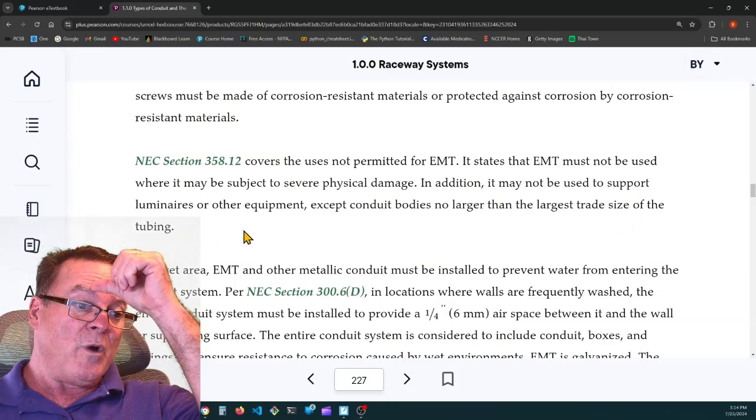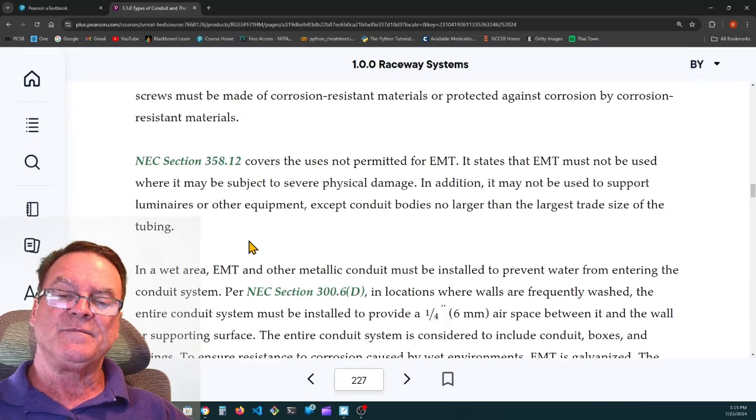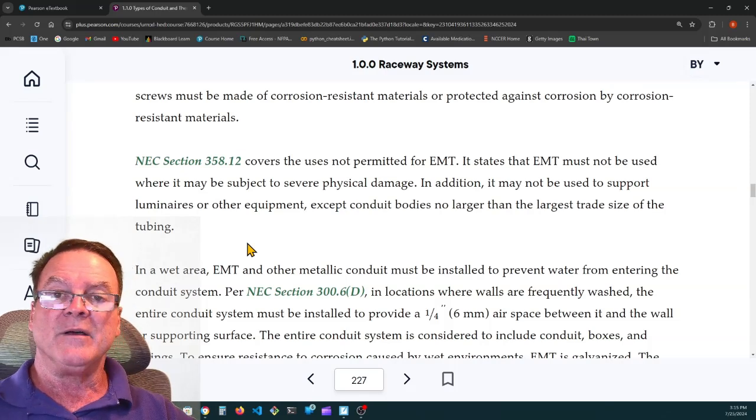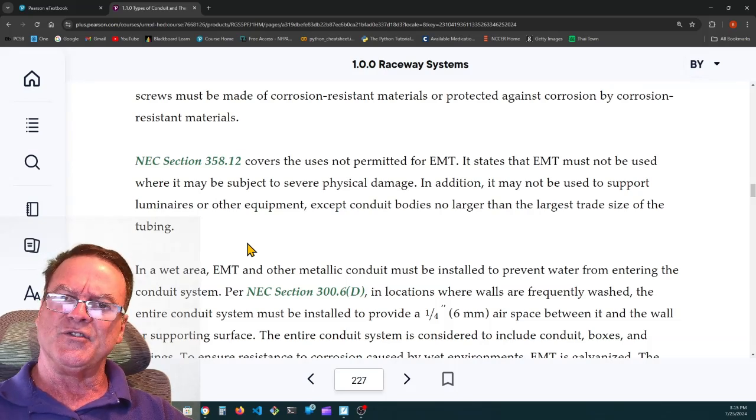So we use down rods to support ceiling fans, and they're 3/4 inch rigid. You can buy them in any length. Oh, they have certain lengths you can get. I think they're even inches, 2, 4, 6, 8, up to a foot, and then I think it's 18 inches, and then it's 2 feet. I'm not sure how long they will sell them.